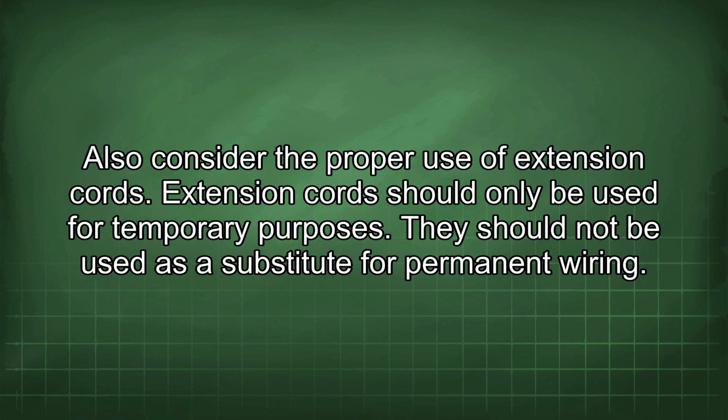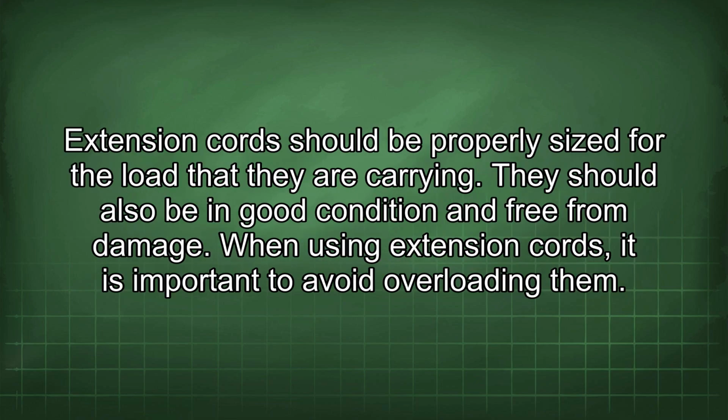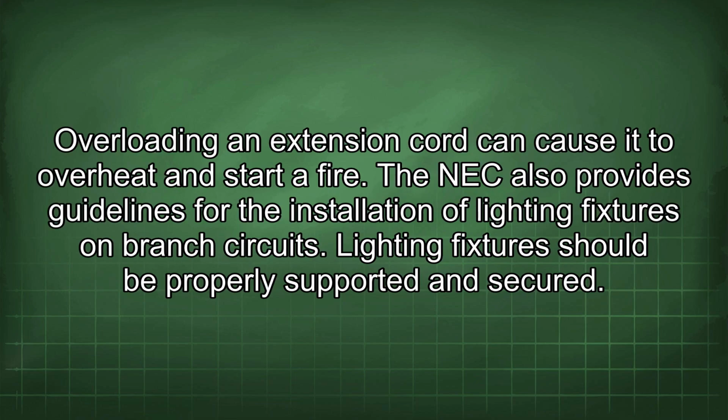Also consider the proper use of extension cords. Extension cords should only be used for temporary purposes. They should not be used as a substitute for permanent wiring. Extension cords should be properly sized for the load that they are carrying. They should also be in good condition and free from damage. When using extension cords, it is important to avoid overloading them. Overloading an extension cord can cause it to overheat and start a fire.